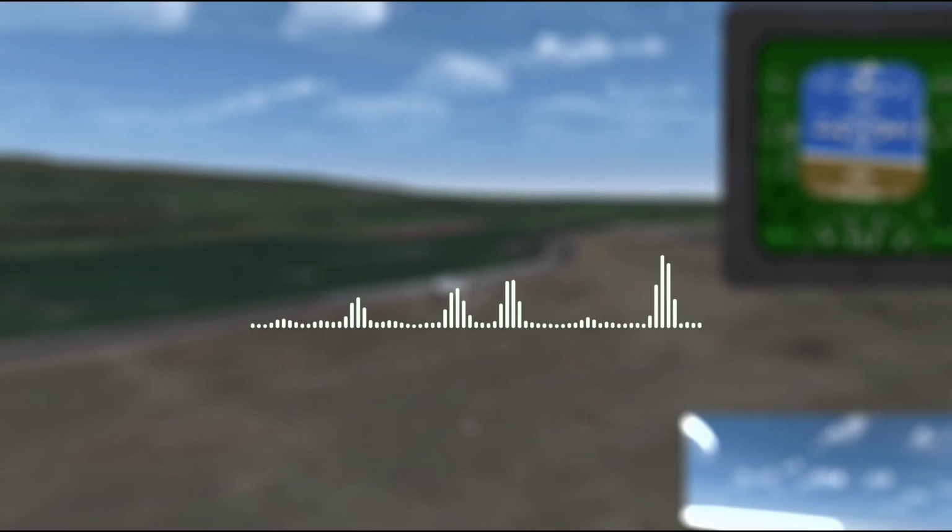Therefore, based on the results of the weight reaction test analysis as well as the longitudinal dynamic response analysis, it is recommended that the CG be located anywhere between 20% and 35% of the mean aerodynamic chord.